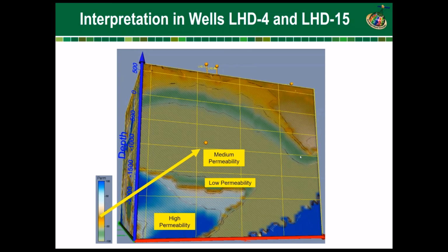Perhaps that is the reason why this entire cavity has zero or close to zero gradient at the top. It probably indicates that this tight rock right here serves as a pretty good thermal barrier. And of course, this is the heat source, high permeability area at the bottom, at very deep horizons below 2,000 meters below sea level.